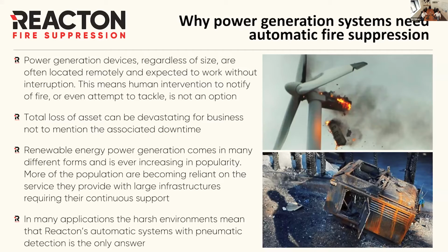You've got hydraulic circuits that deal with the blade orientation, the tip orientation you can see in the top right-hand corner, and the pitch of the blades is all controlled hydraulically. So you've got hydraulics, you've got a hydraulic motor. You've obviously got the electrical generation side, so you've got the motor generator and the control equipment for it, you've got grease and oil for lubrication of bearings, and you've got a hot environment that it all works in.